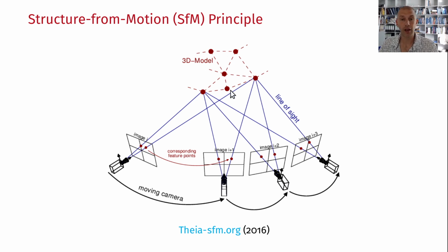So you're solving a matrix at the same time for the 3D position XYZ, for the camera distortion, and also for the camera location. So these are many parameters that you're trying to solve, and there are issues with solving such a weakly defined matrix system. So the idea is automatically identifying key points on your image, because for the structure from motion